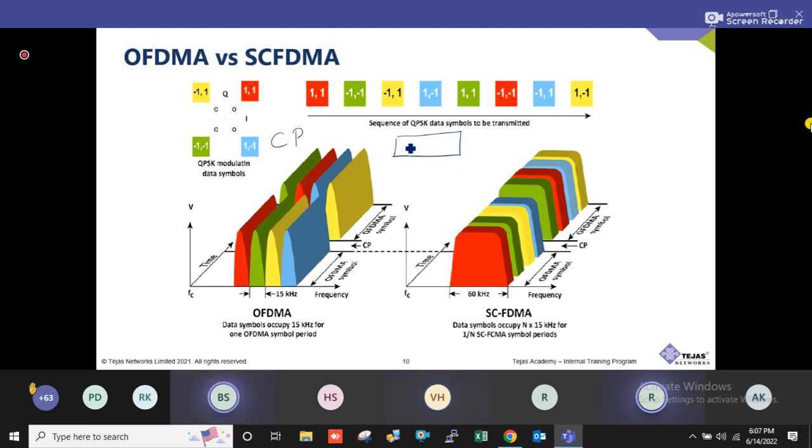See, what is happening is, let's say this is my data. Whenever there is something called intersymbol interference, typically if you speak in an echo channel environment, the last part will be more affected in the echo when compared to the first part of the data. So this is the first part. The last part will always have a lot of echo or ISI, intersymbol interference effect, when compared to the first part of the data.